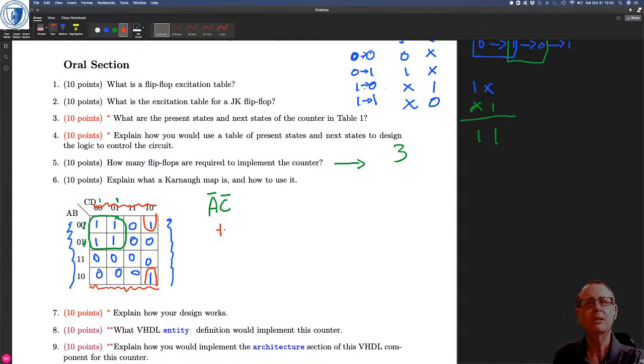Then it's a sum of product, so there's the product, there's the sum, and on this one, sorry, let's go here, so 0, 0, and 1, 0, so the thing that's changing is A, and the thing that doesn't change is B is 0, so it's a B bar. And then on this, it's the 1, 0 column, so that's a C D bar. I didn't do the same pattern for everybody. I gave the same grouping of 4 and the same pair-wise, but that's what I was after. I was after being able to simplify.